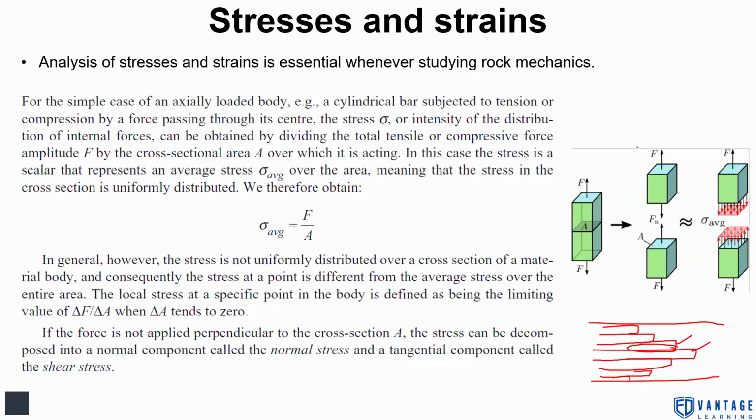So the shear component of this flow will be on the layer between two slices of division. In the same manner, when I deform the body, maybe say by compression, the body deforms in such a way that a shear failure plane appears on the body, where the sample actually fails. So we take two stresses called normal stress and shear stress, and shear stress will be acting on the shear plane or failure plane.